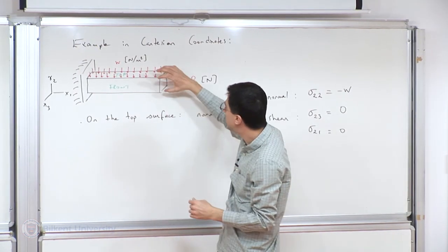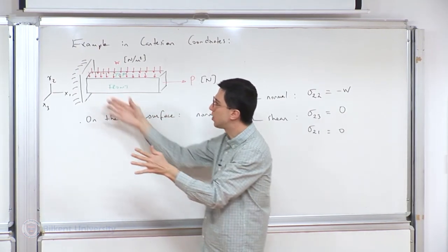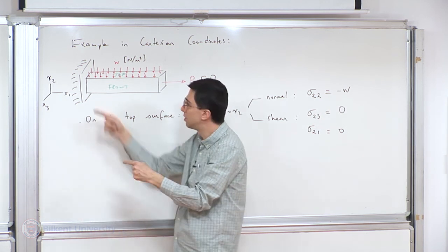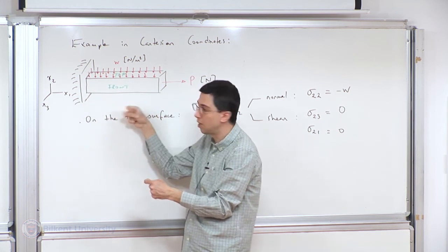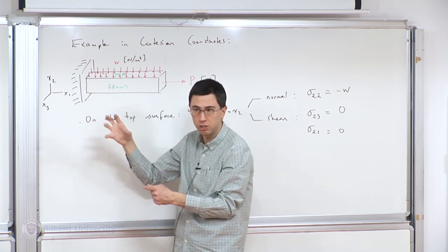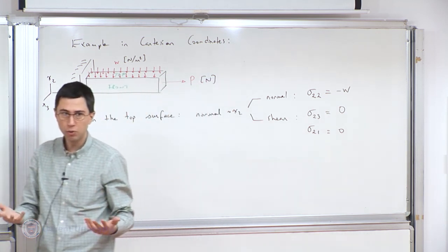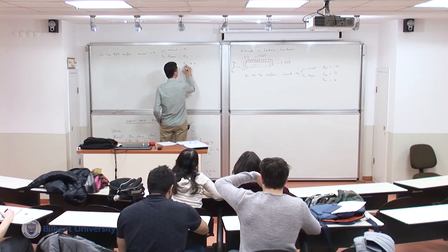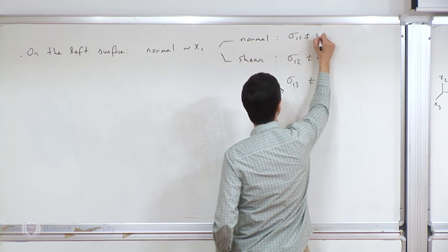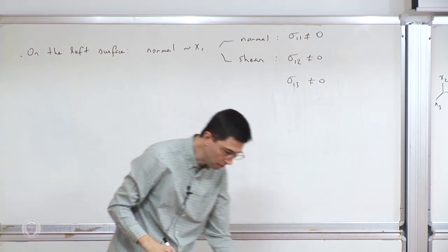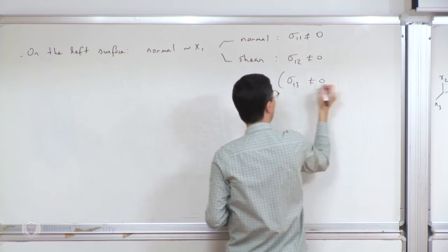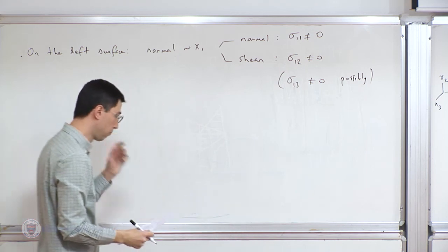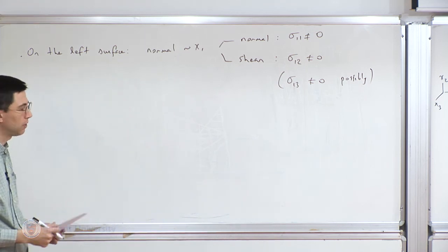Well, but you can imagine that I'm trying to deform this thing, pull at it. So eventually, perhaps due to Poisson effect, it is trying to contract along the 3rd direction due to deformation, but I am constraining that deformation, right? It cannot contract, and to resist that contraction, there needs to be some stress. So even this is possibly non-zero. So I cannot say from the outset for sure that any of these are non-zero, okay? So possibly this is also non-zero, but the other two, for sure, I'm very confident that they are